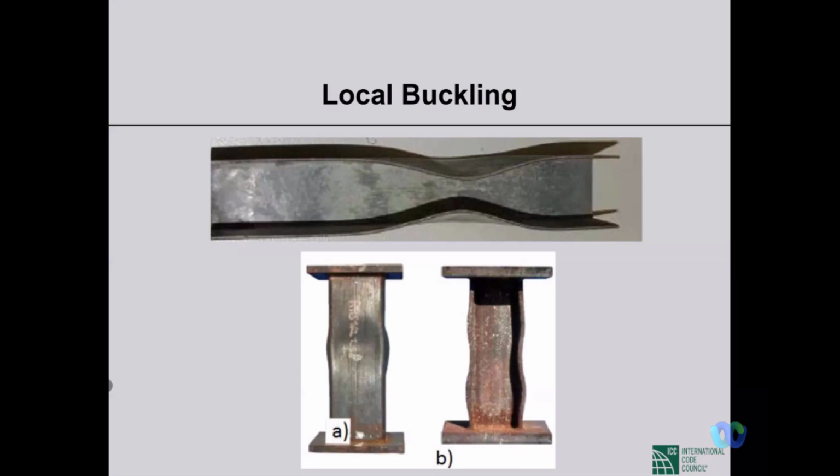Now, when the sections are thin and the members are long, in case of very thin and long sections, they become slender, right? L by r ratio, you all know, slenderness ratio. So steel sections tend to be slender, and whenever compression is induced in whatever form, that tends to make the steel sections buckle.